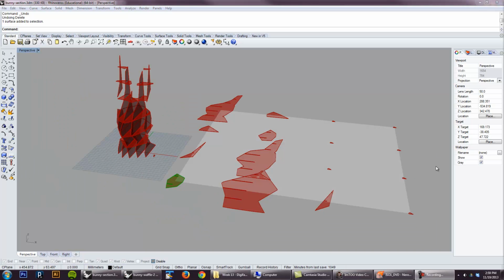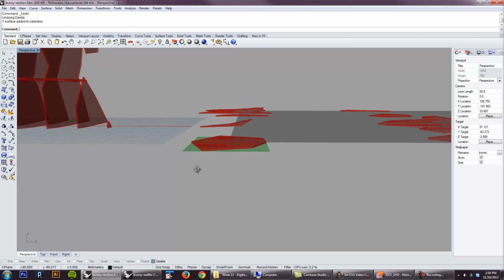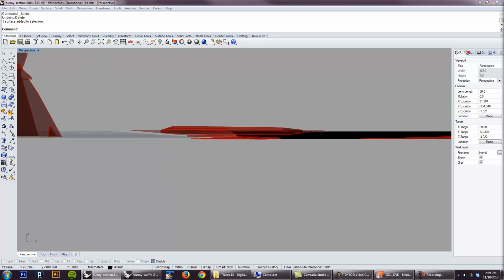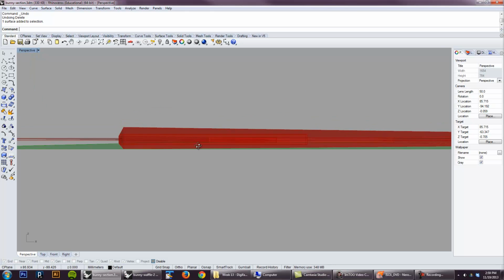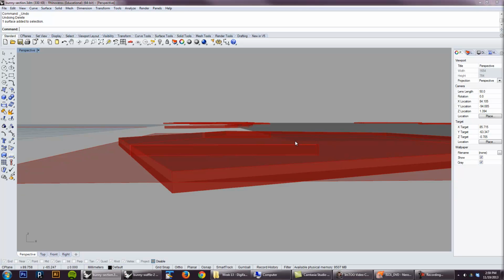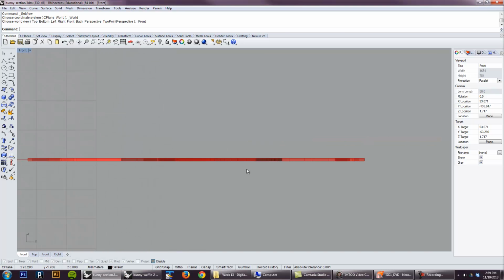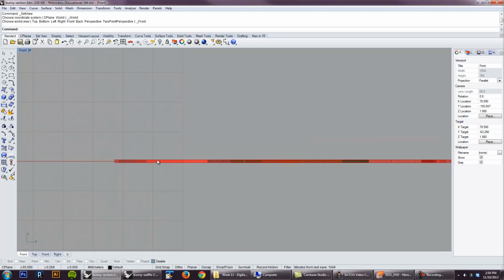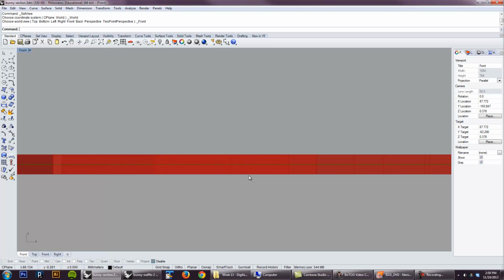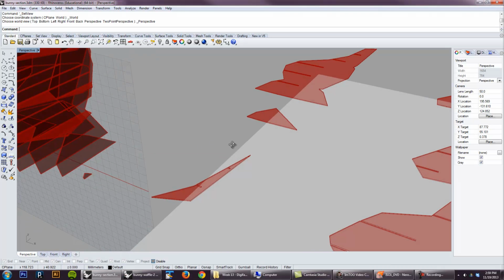So in order to flatten it, a technique that works that's not too convoluted is to basically create a plane that is going to intersect that object, and that plane is actually going to be centered, like, halfway. It's kind of hard to see. Let's see if I can make this clearer for you. So, see the green line here? It's actually halfway inside the object, and that's going to ensure a clean intersection.